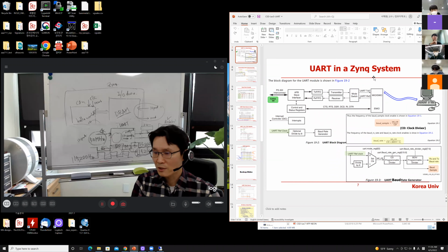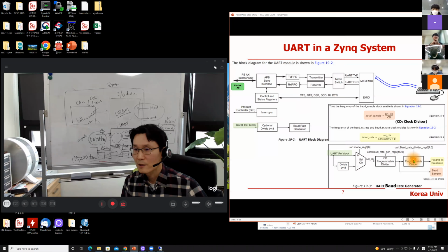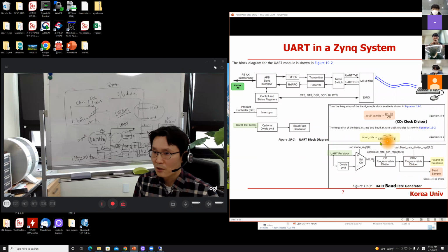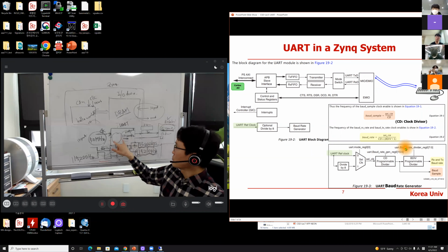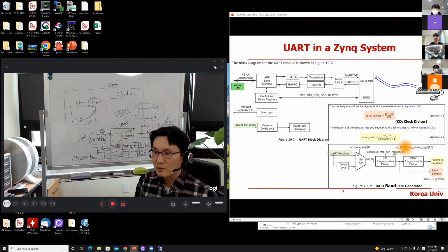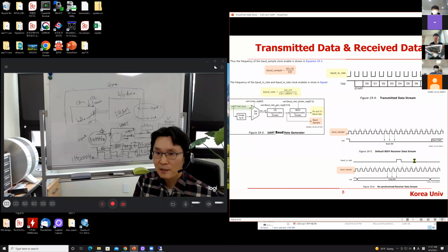So it is all about checking out this technical data sheet. Which register do I have to touch for this one, to touch this BDIV? According to this formula, the hardware mechanism, the denominator is CD multiplied by this one, BDIV, the baud rate divider register. Two different registers, the generation register and the divider register. You play with these two registers to cook up this value. It's very simple, right? You need to cook up this output by playing with CD and BDIV.